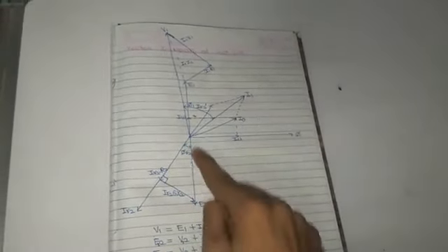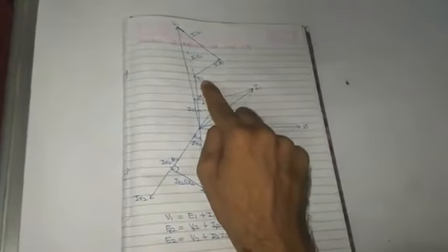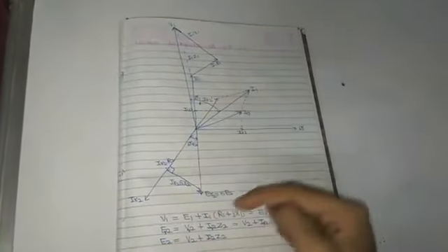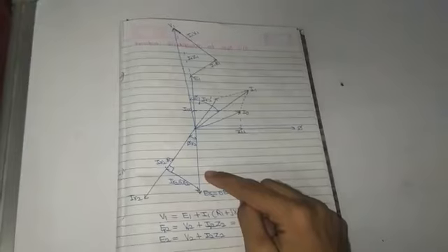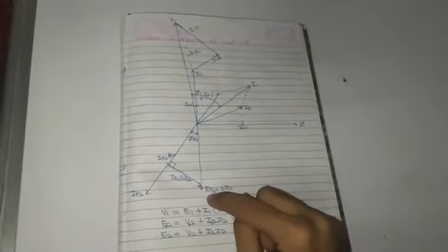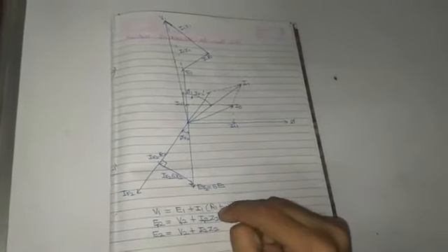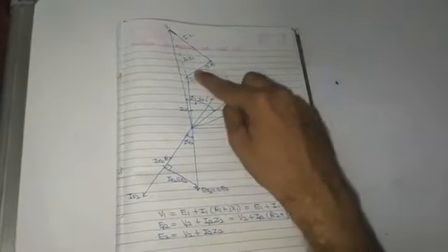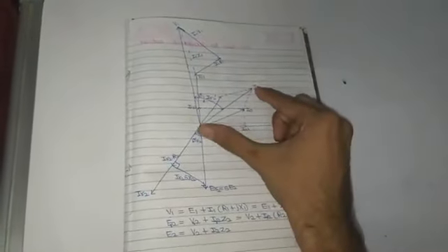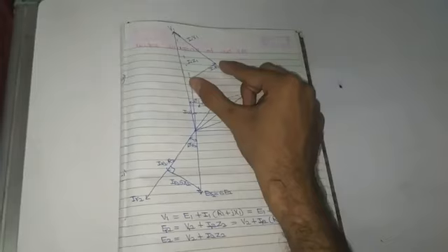And this is ER2, which equals S into E2. E1 is the stator induced EMF per phase and E2 is the rotor induced EMF per phase, but under running conditions it is ER2, the rotor induced EMF per phase. So ER2 equals S into E2. And what about this I1 R1? It is in phase with the current I1 because it is the stator resistance R1.